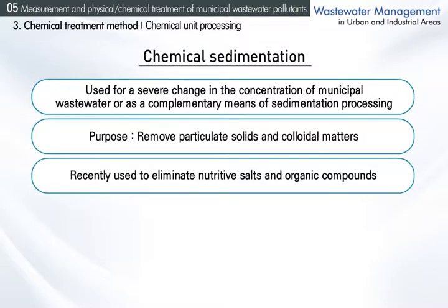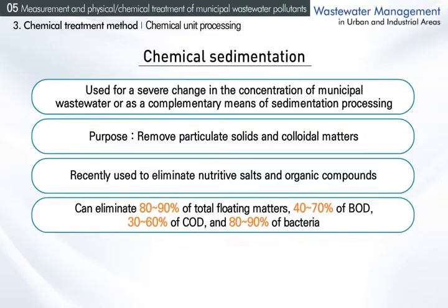It has recently been used to eliminate nutritive salts and organic compounds, such as nitrogen and phosphorus, and can eliminate 80 to 90% of total floating matters, 40 to 70% of BOD, 30 to 60% of COD, and 80 to 90% of bacteria by sedimentation.